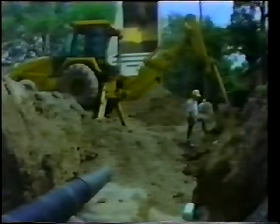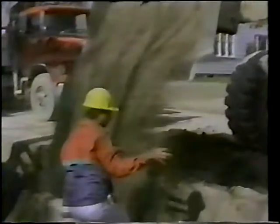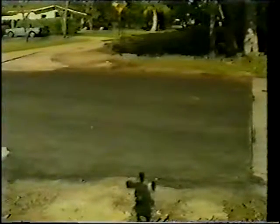A minimum cover of fill should be specified to protect pipe from the effects of heavy trucks and construction equipment. Where pipes will be located below pavements, the soil should be compacted to the top of the trench to prevent settlement.